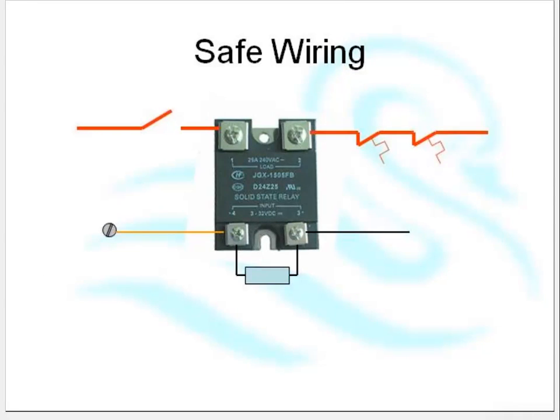Now, when we wire it, if we're wiring to a heater, for safety, regulations state that on the load side we have to have isolation. You're not allowed to have isolation on the control side, because if it fails, it can just as easily fail on. So you have the isolation on the load side, and also if you're outputting to a heater, there have to be 2 thermal overloads on the load side of things. Those thermal overloads are designed so that when the thing fails on and the heater catches fire, the thermal overloads will trip it out.